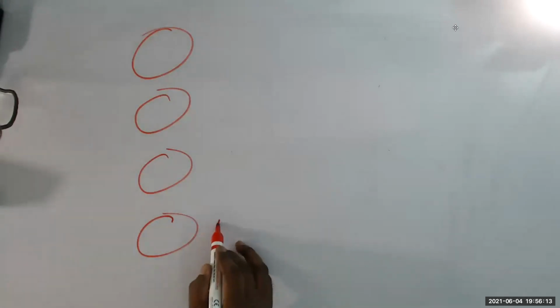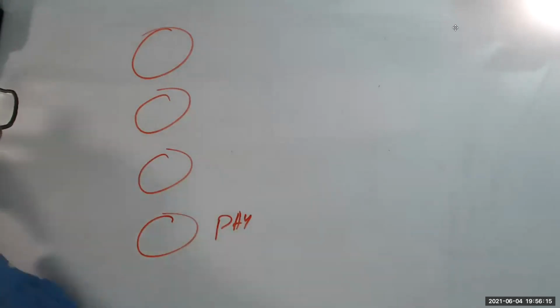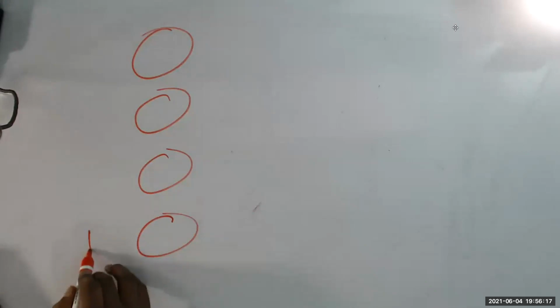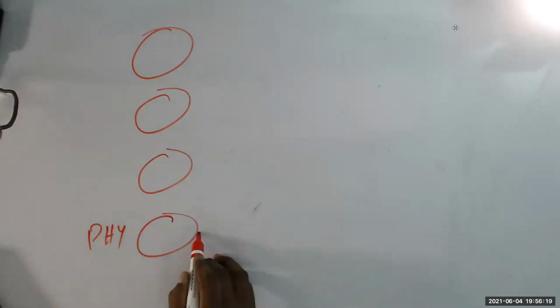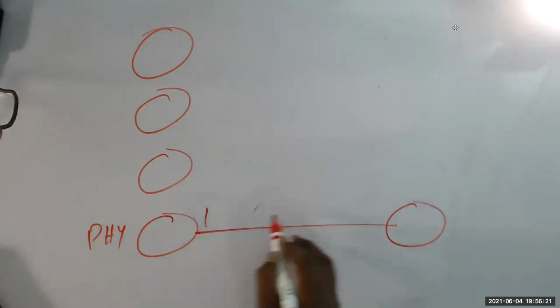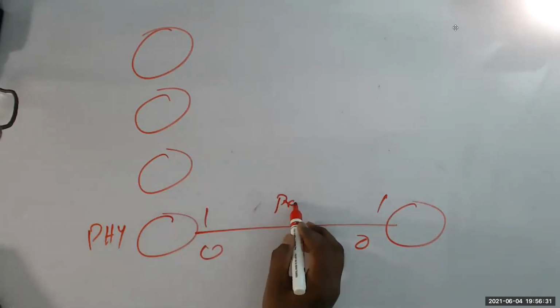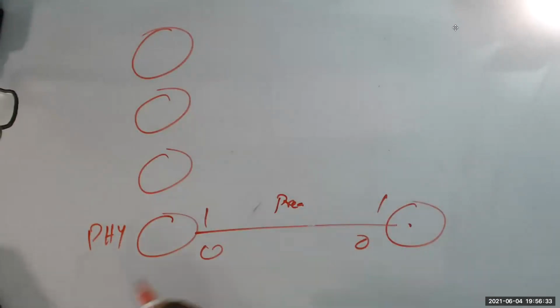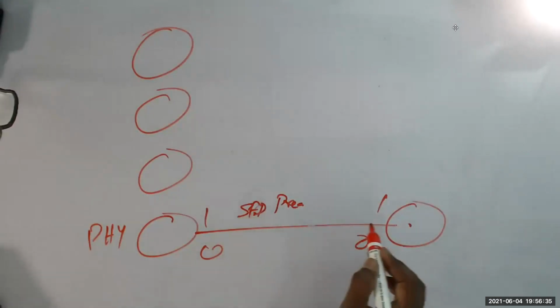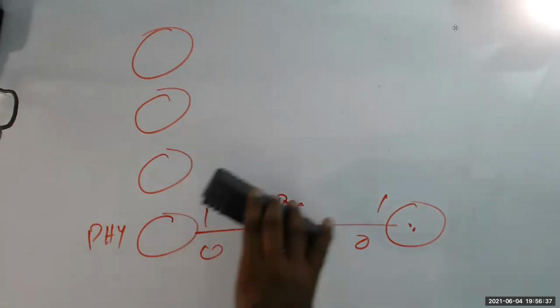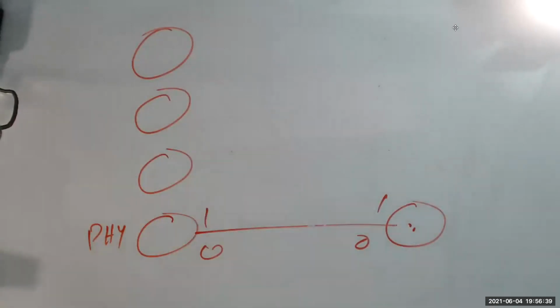Now you know that there are four. One is the PHY. The PHY's responsibility is to send the data there. If it's a 1, it means 1; 0 means 0. He uses so many methods, whatever method. He could send it over wire or wireless or fiber. It's the PHY's responsibility, and it also sends the preamble for clock synchronization and the SFD to make sure. So the PHY does as much as possible.